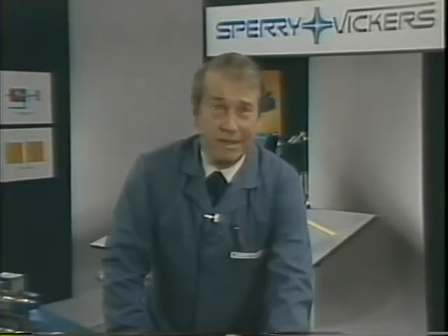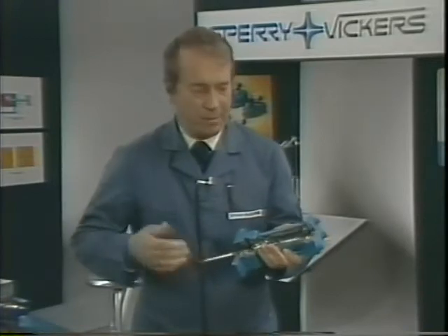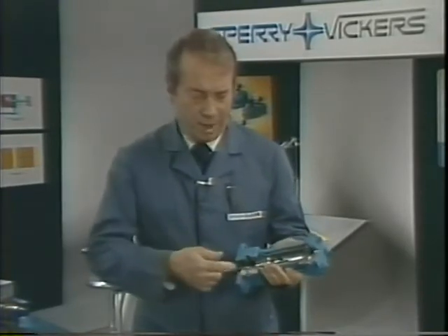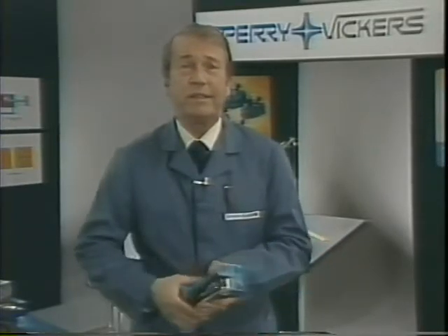Basically, there are two motions we can achieve hydraulically. We can move something in a straight line, or we can make something rotate. A cylinder, or linear actuator, provides the straight line motion. It can be single-acting, like a hydraulic jack, where the weight of the car brings it back down, or double-acting, where the piston is forced both forward and backward in its bore by fluid under pressure.